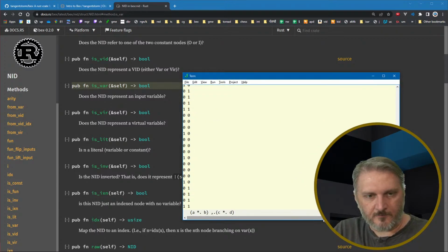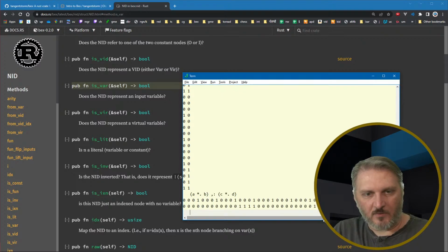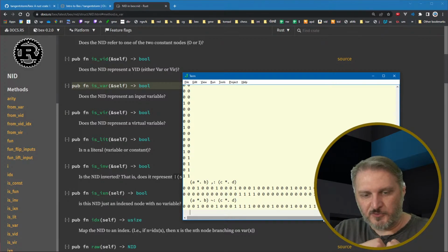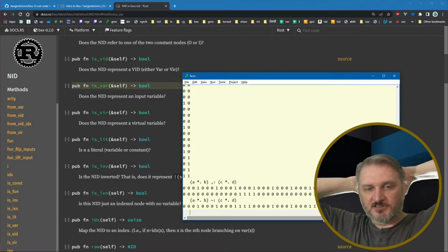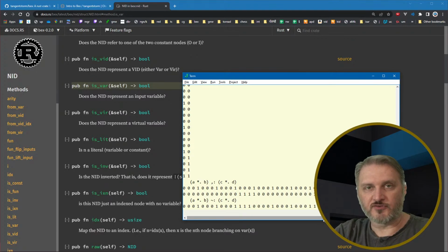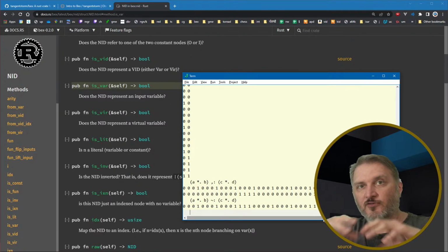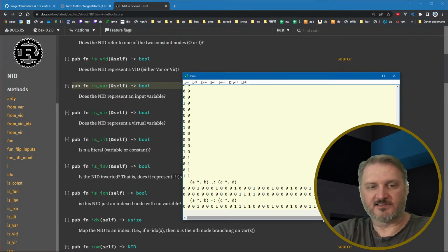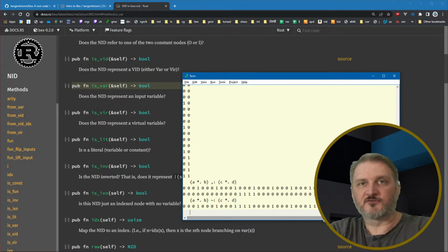You put them side by side. Well, you want to XOR these things together. You get this truth table. And so you can just do that operation directly on the truth table. Right? And so any two 32-bit truth tables can be XORed, can be ANDed, you can do all those operations directly, and you save yourself the work of constructing this weird graph. All right. So that's the reason for having these.